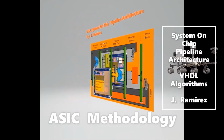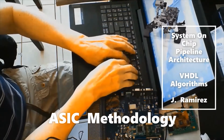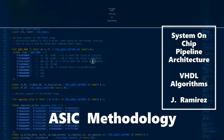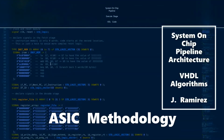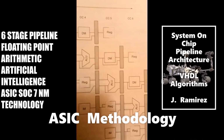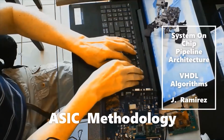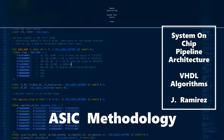The execute stage is tasked with taking the data and actually performing the specified operation on it. The execute stage consists of the arithmetic logic unit, a determined branch unit, and the forwarding unit. The execute stage connects these different segments together so that the arithmetic logic unit will process the data, given inputs chosen by the forwarding unit, and it will notify the decode stage if a branch is taken.